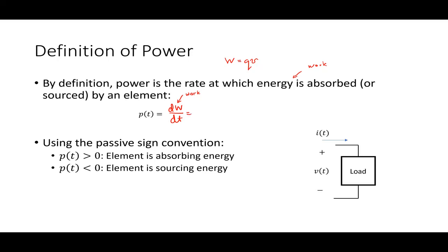So the way we derive power is we say that's the rate at which energy is used, so it's the rate d(VQ)/dt. If I think of a charge having a particular constant voltage V, I can write this as V times dQ/dt. So if I have a charge with a particular voltage that is moving, this becomes V times I, because remember, dQ/dt is I.